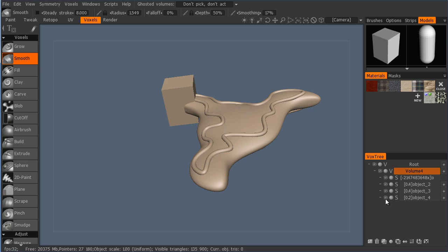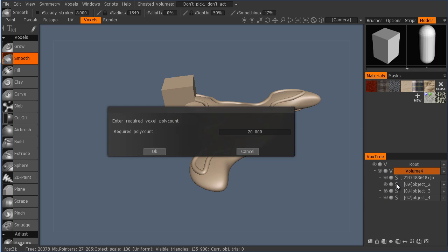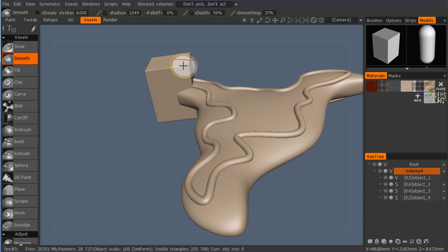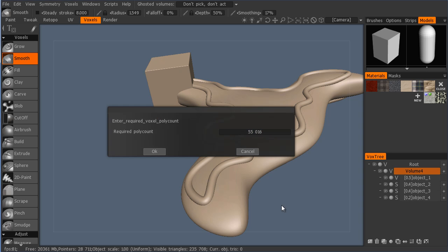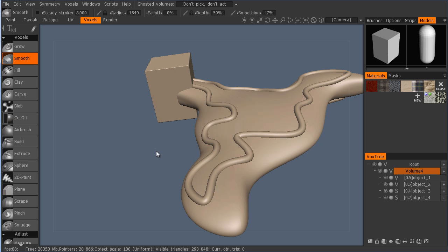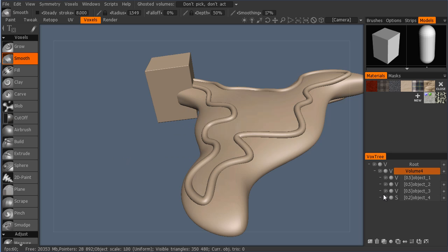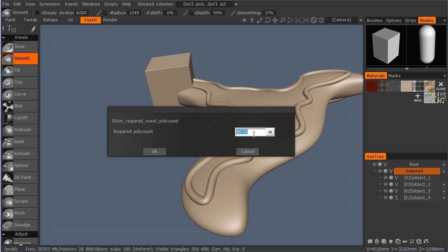You can voxelize these objects quite simply by setting the required poly count, I don't know, 100,000. It works easier if you're just going to import it as a, so that's now been voxelized. You can see the corner has got a slight radius. Let's do the same with that. I don't know, let's make it 100,000. Remember that your experience of limitations based on what you know about Rhino don't actually apply when it comes to 3D-Coat. It's a true 64-bit mesh modeler or voxel modeler, so you don't have the same limitations that Rhino has.